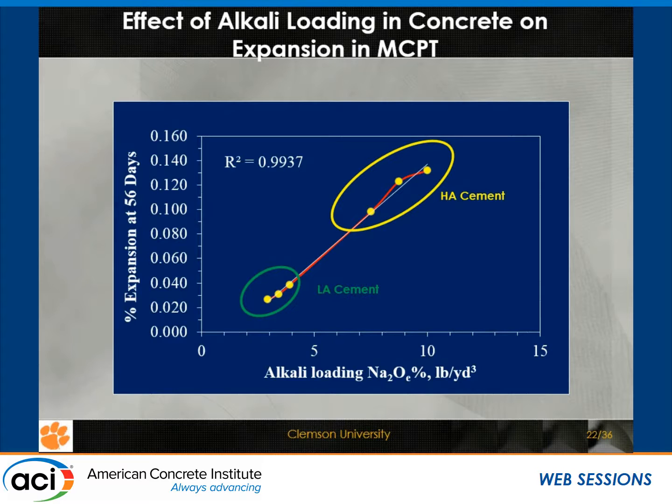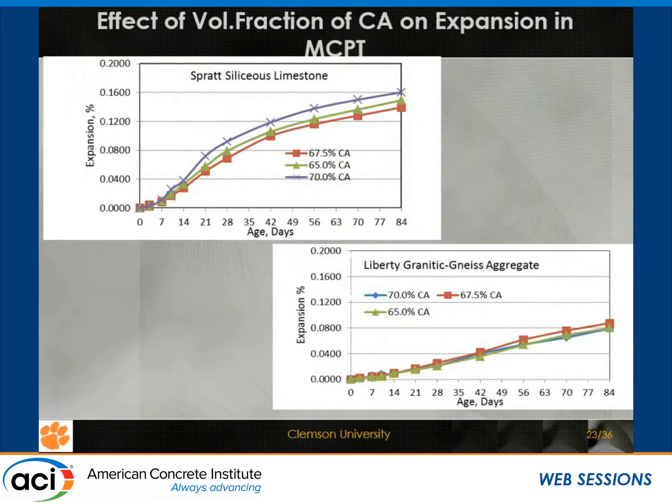So if you look at the typical limits that we use in terms of alkali loading, about 5 pounds per cubic yard, that again matches up very well with the expansion limits that we typically follow. So another reassurance that it's possible.